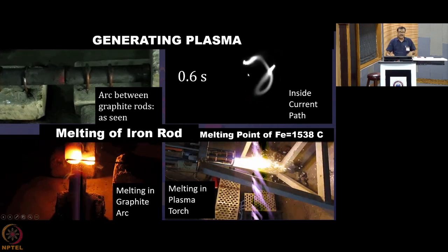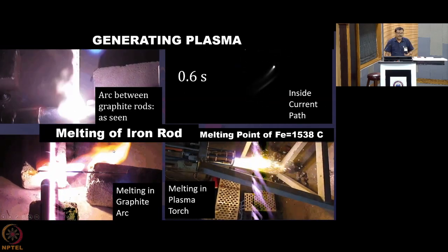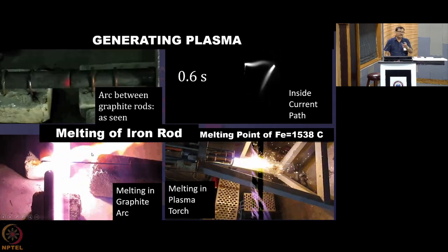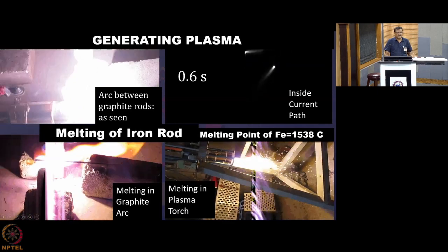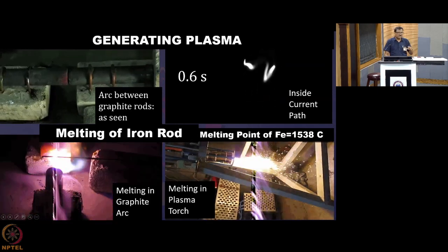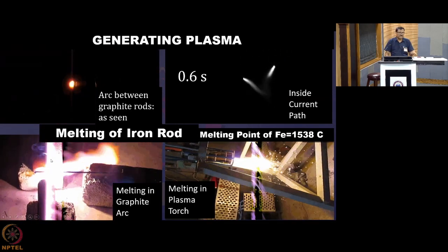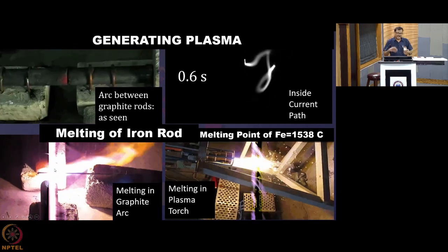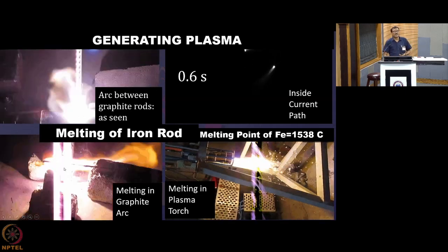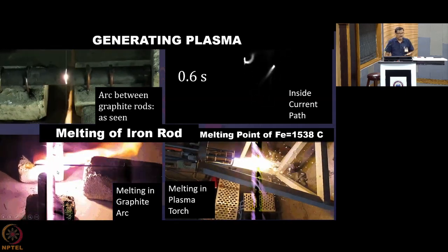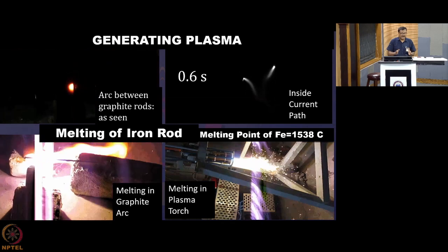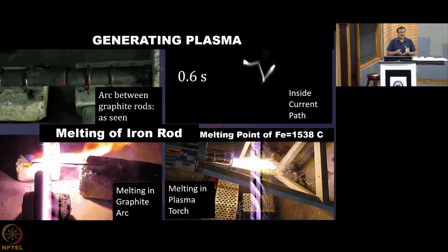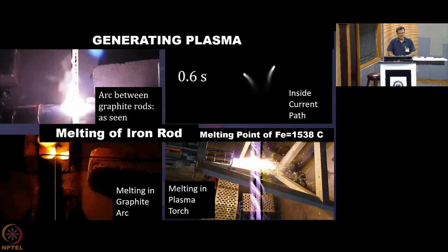So when your arc is moving randomly like this, it cannot be in touch with the rod for a long time. It is now hitting here, next time it will be hitting somewhere else, and next time somewhere other place. So it is not able to continuously hit the rod in a persistent manner. The same way our finger is not burned, the rod is not heated up. So what is required? It is required to stabilize the arc in a fashion that it can consistently and continuously heat the gas that is passing through that zone.